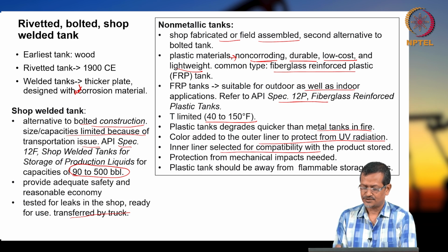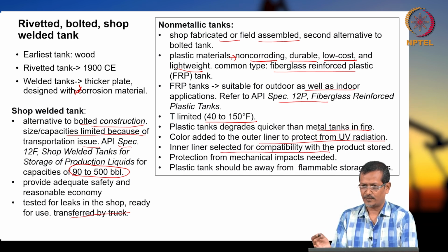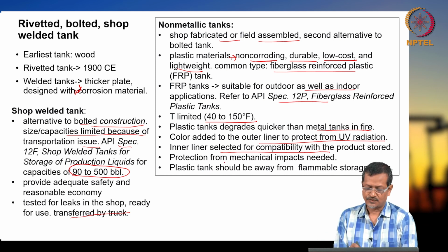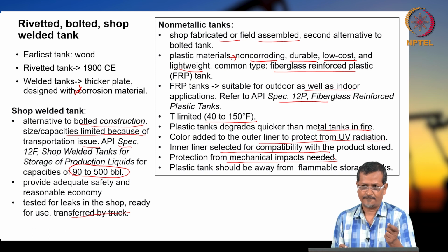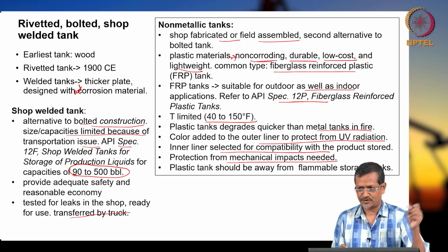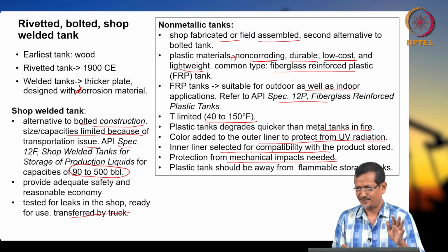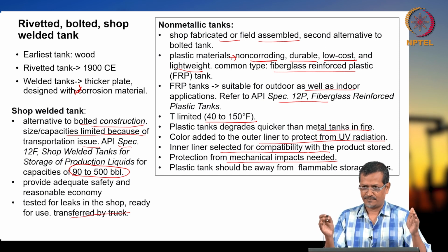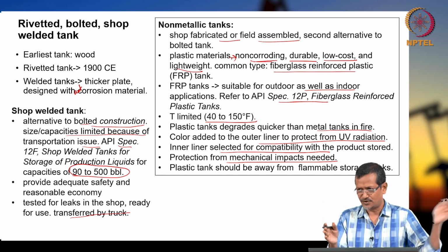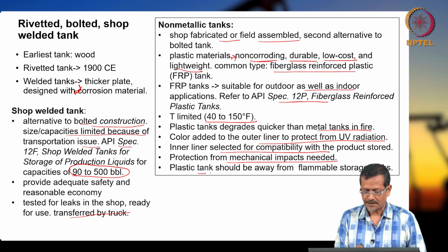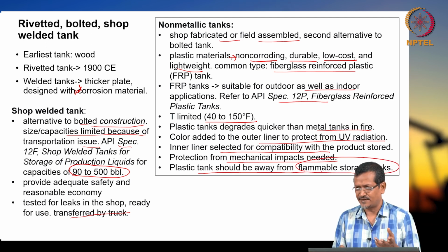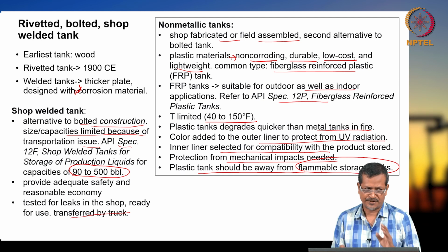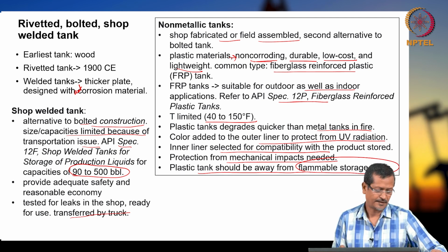The inner lining should be compatible with the product, whatever oil you are using. So, that should be compatible. Okay. So, protection from mechanical impacts is also needed, because plastic is a softer material. If some impact happens because of stone throwing or anything, okay, some mechanism should be there so that the tank does not get hit. A plastic tank should be kept away from flammable storage tanks. Okay, if there is any flame source, then a plastic tank is much more dangerous than metal systems.